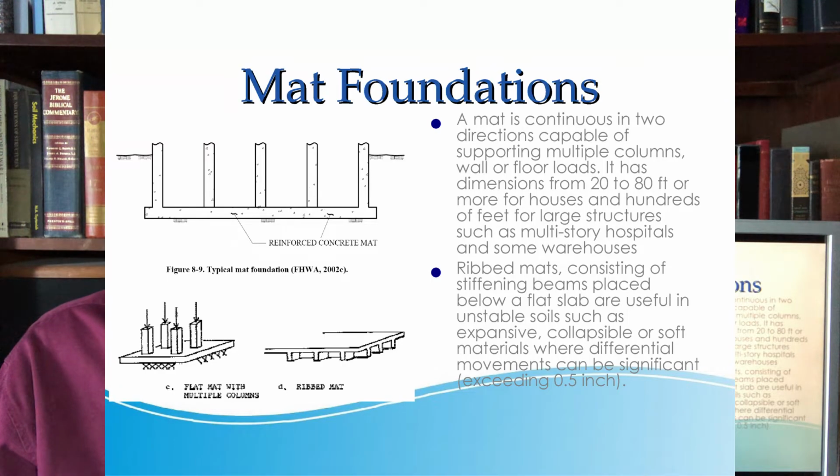Mat foundations are very large foundations, with dimensions from 20 to 80 feet. They are used normally for large buildings, and usually you see them in soft to medium soils.